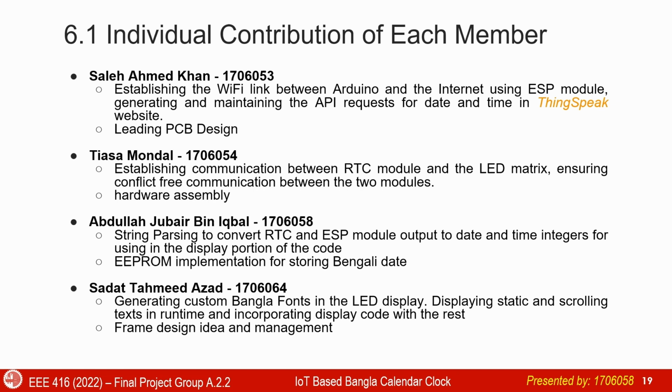For me, I have done the string parsing to convert the RTC and ESP module output to date and time integers for using in the display portion of the code, and I have implemented the EEPROM for storing the Bengali date. And Sadat generated the custom Bangla fonts in the LED display, displaying static and scrolling text in the runtime and incorporating display code with the rest. Frame design idea and management was also done by him.